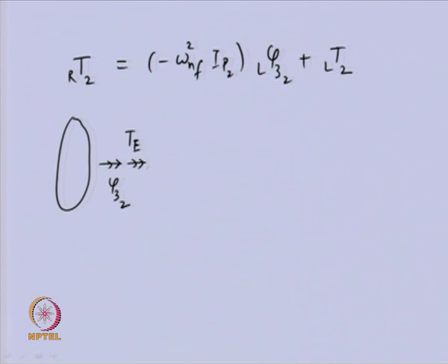Because we had earlier this also in the positive direction and the left side of the torque was negative direction, you can see that this particular torque will find a place along with the torque at disk 2 in the right side here. If we transfer that to the other side, we will have this external torque coming here, and we had another relation, that the angular displacement in the right side of disk 2 and the left side of disk 2 are the same.